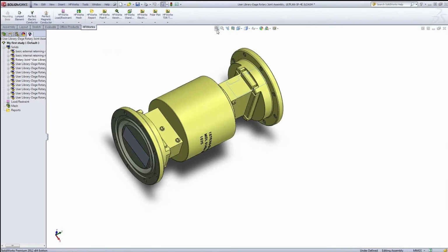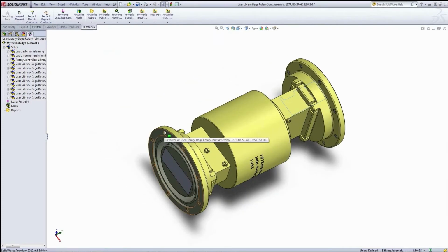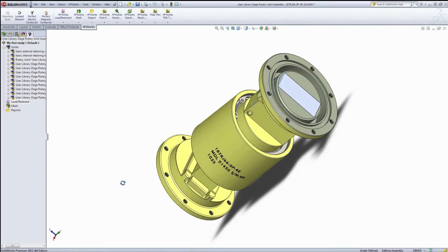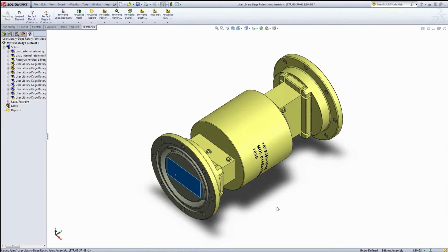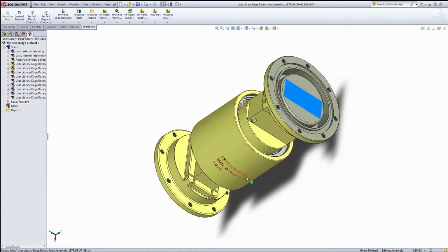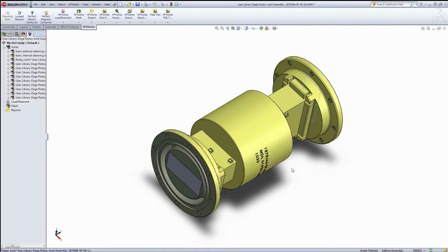All right. So let's say this is the material definition part that's done. When all of the materials are done, you see the check mark, so this is done. So the next step is boundary conditions. Now, if we look at this structure, this is a 2-port structure. So this is port 1, and this is the 2nd port. So I need to basically tell it that I have 2 ports.